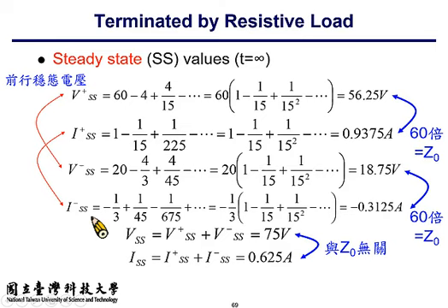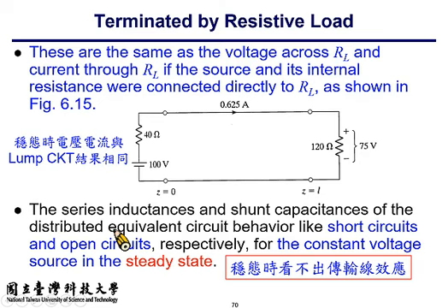So the total voltage, which comprises forward-going and reverse-going components, does not have to obey the characteristic impedance ratio. Nevertheless, all the forward-going and all the reverse-going components should abide by the voltage over current ratio, which is the same as the characteristic impedance.